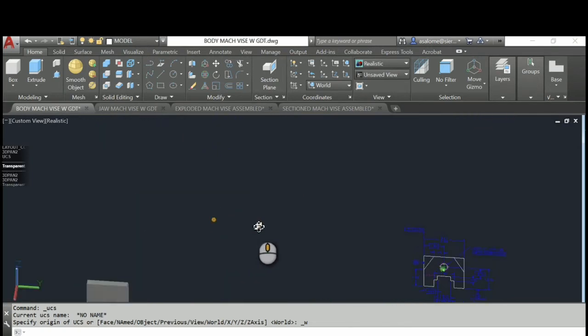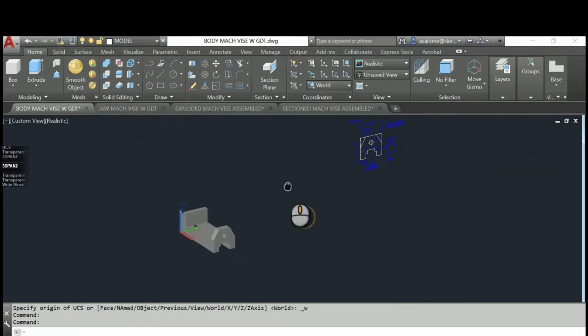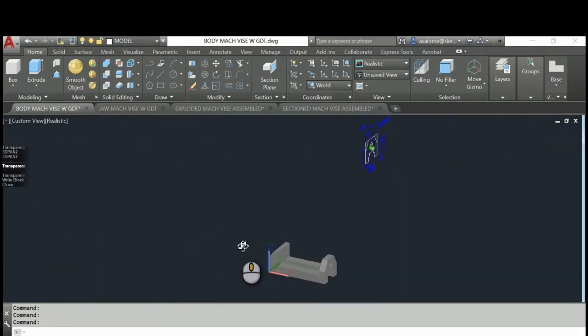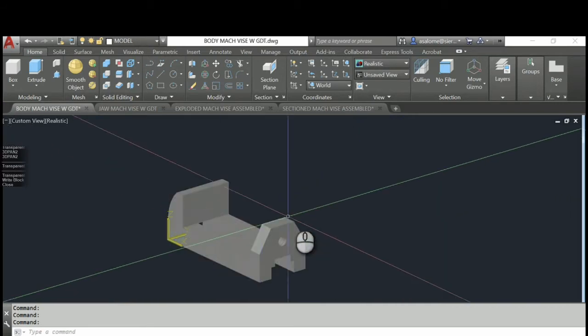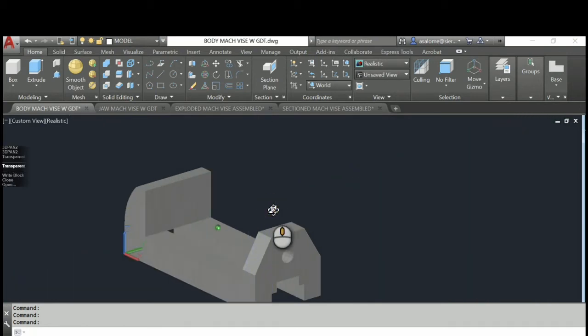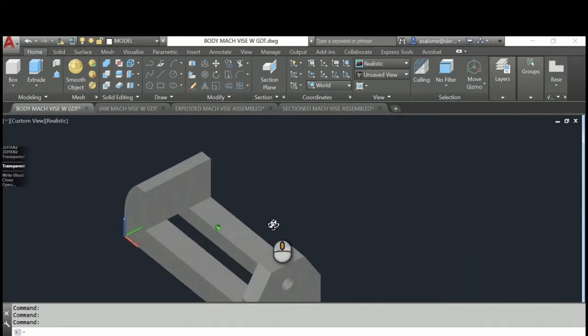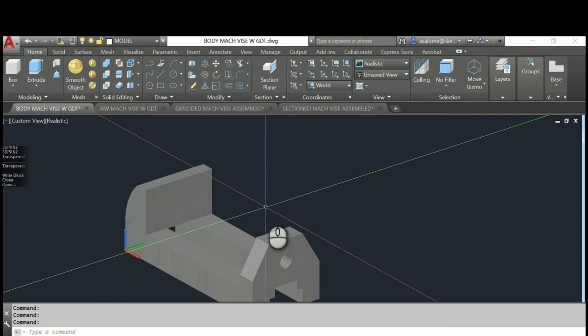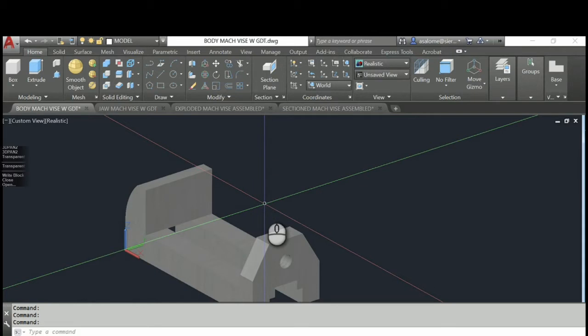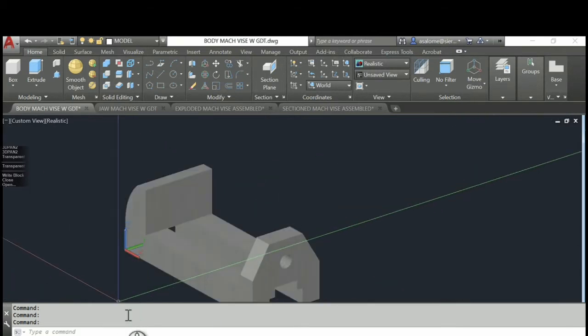And what we're going to do next is what is called a W block. Now, depending on what version of AutoCAD you're using, what AutoCAD textbook you're reading, sometimes people refer to that as a write block, W-R-I-T-E block, because it writes out a file. Some people call it a world block. Either one of those are acceptable terms. We're just going to call it W block. And that's exactly how we're going to get it: we're going to type in WBLOCK at the command line. What that's going to do is bring up this dialog box.